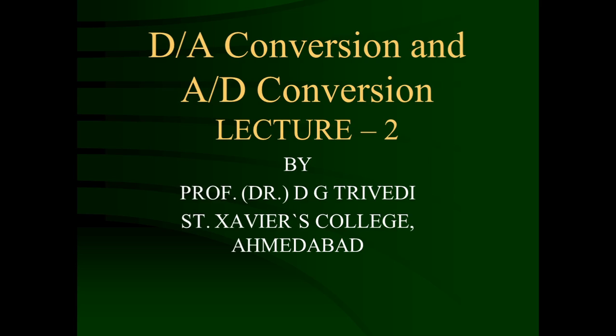That means many values of resistance we have to utilize. Moreover, the current passing through each branch is going to be different. The current passing from the MSB for a 10-bit system is going to be 500 times the current compared to the LSB, and that is also a disadvantage of the resistive divider network. Moreover, precise values of resistance are required, and precision will cost more. That means more cost is going to be there for the resistive divider network.